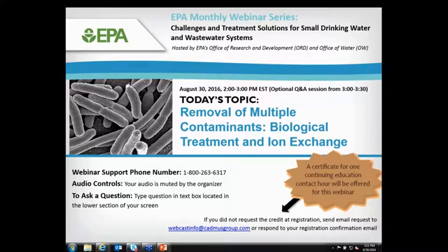When you're running a downflow biological treatment unit, one of the things you do is keep an eye on your head loss just like you would in a regular rapid media filter. Once your head loss goes above some predetermined level, you backwash, and in our experience with our pilot units, we're looking for the exact same things that you're looking at when you backwash a rapid media filter designed for particulate control. So we're looking at clarity in the backwash water. We're also keeping an eye out for formation of mud balls and